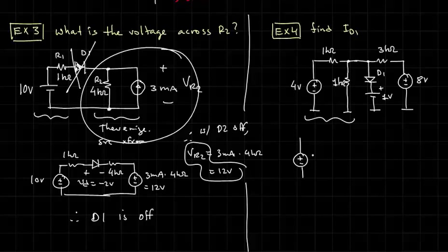It certainly will simplify the circuit, right? So to Thevenize, you look into the left here with the source off, and you see 1K in parallel with 1K. So I have a half a K here. And the open circuit voltage I would see is 4 times the voltage division ratio, which is 1 over 1 plus 1.